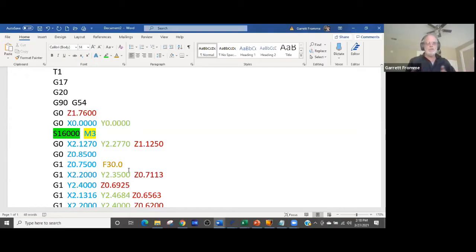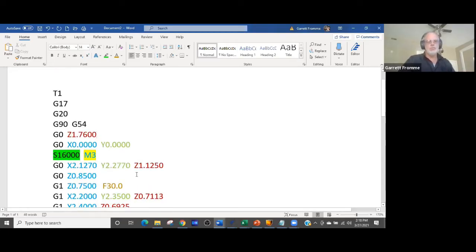However, every CNC router brand has its own post processor. That's why if you have Vectric and you open up the post processor list, there's like 200 of them in there. That's because a post processor has been written for a specific machine, and so its output, which is what you're looking at on the screen here, gets punched out in a certain format.